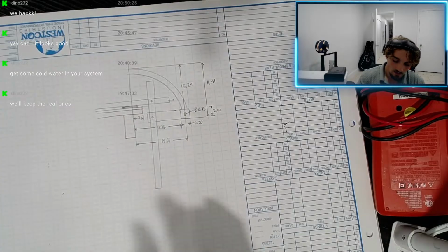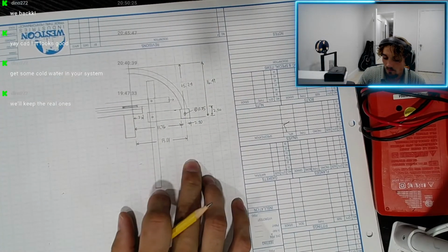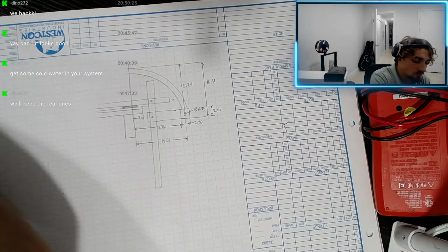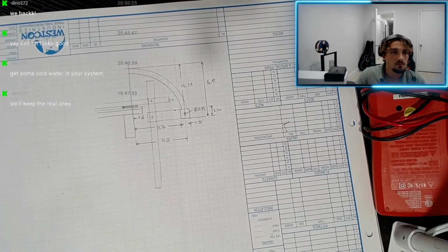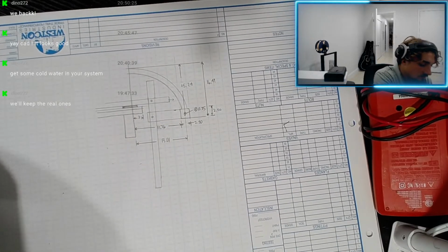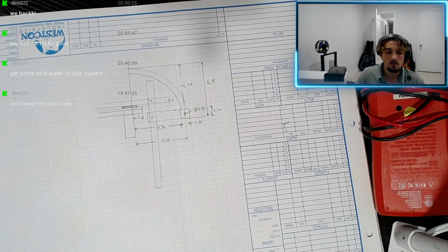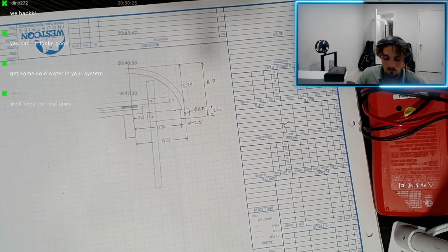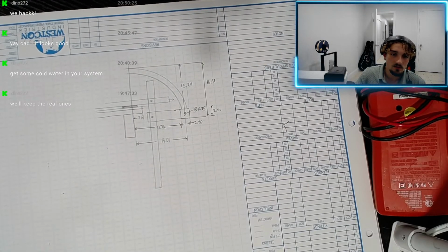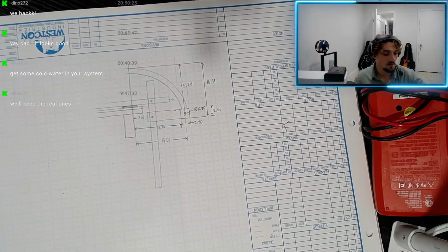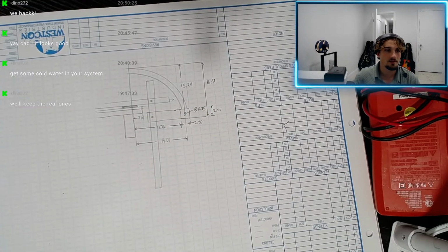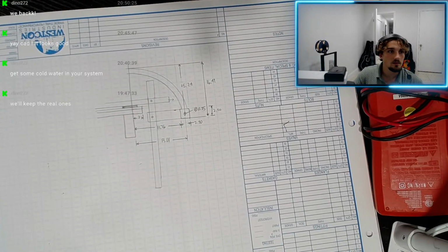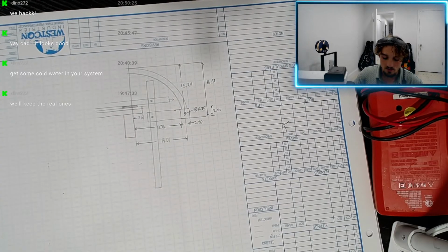Alright, make this guy 2.5. Let's make him 2. Let's go 1.5. Yeah, like that. Check. Okay, so now we do that. Exit sketch. Let's make it 0.5 inch. Half an inch. Check. Okay, we're gonna do another boss extrude.